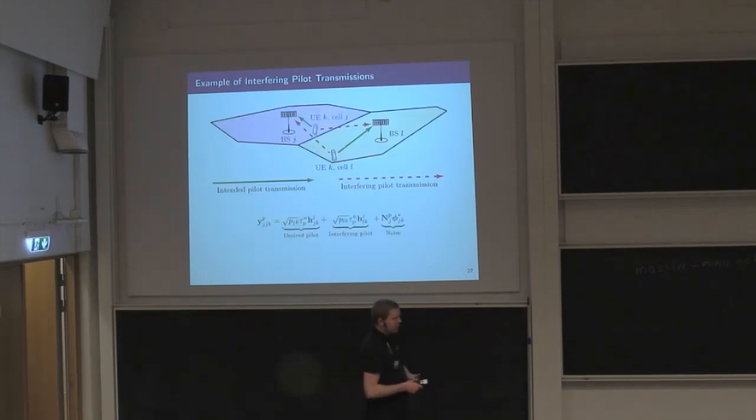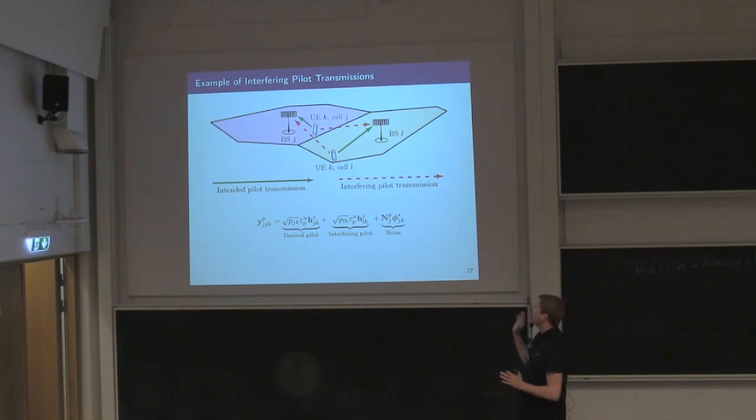So look now at the first time of what we call pilot contamination effect, where we say that two different users are using the same pilots. Then the received signal at base station in cell j is the sum of the channels from two users. You have their powers, we have the tau_p, the length of the pilot sequences, and we have some noise.